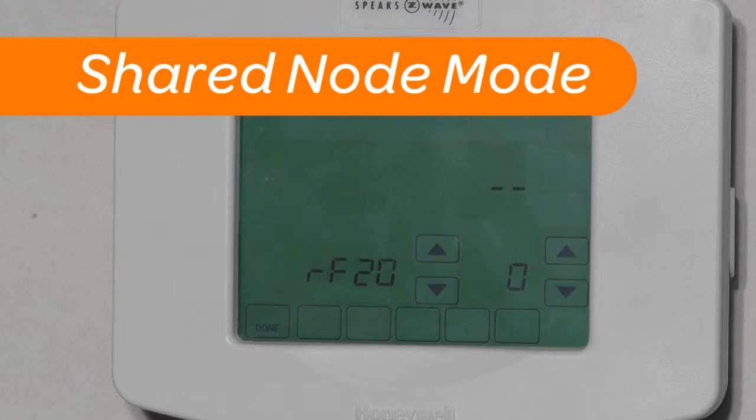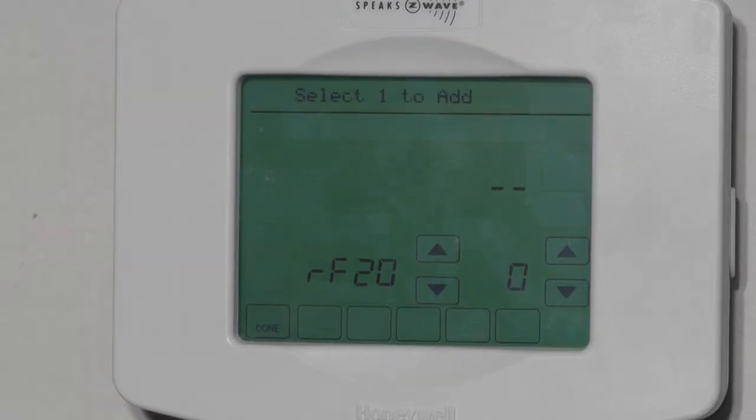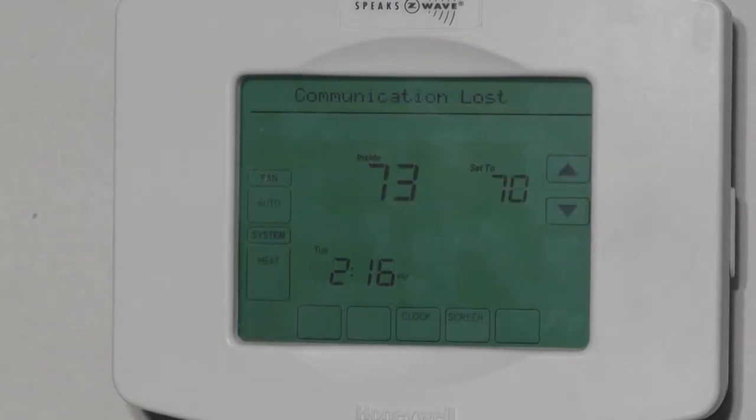If this mode is enabled, all thermostats in the home will function as one. So if one thermostat initiates cooling, the other thermostats would also turn on to cooling, thereby acting as one thermostat to avoid warm and cold spots in the home. Once programming is complete, press the Done button.